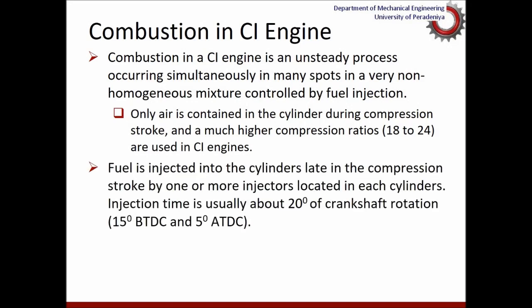As I mentioned, the fuel is injected into the compressed air at the end of the compression stroke. So the pressure and temperature are very high in diesels at the time of injection, and the injection duration is about 20 degrees, depending on the engine design.